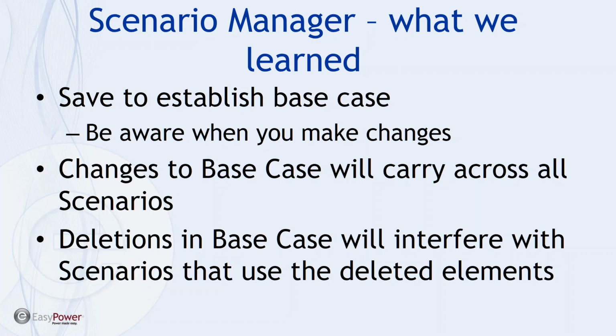Okay, questions. There's a question about no sound to start with. Sorry if that was a problem. Do you have a general strategy for developing an exhaustive list of scenarios that will be needed in a typical design? That was my reason for asking the question and for bringing up the topic. If you go in and look at this large file, motor contribution was significant, but it didn't really change the results, at least in the system as it existed, because the devices that were highlighted as violating equipment duty compliance did so whether there was motor contribution or not. So the scheme, in my mind, is looking at your equipment duty report.